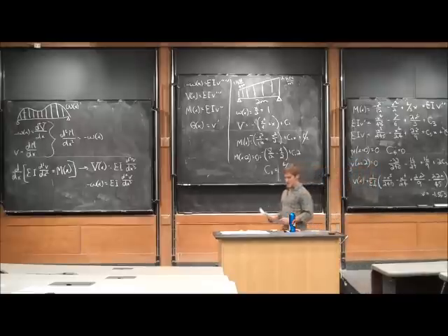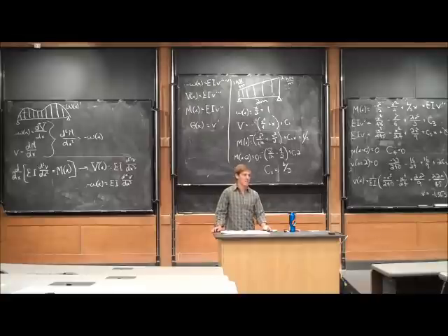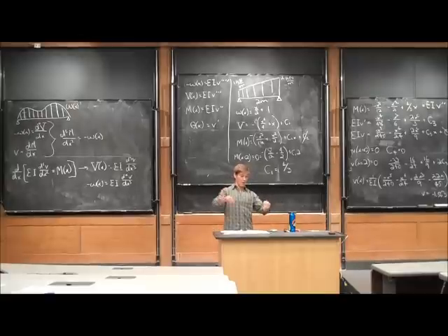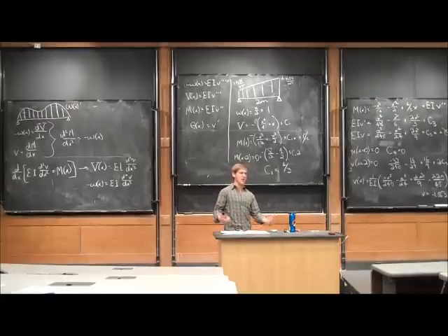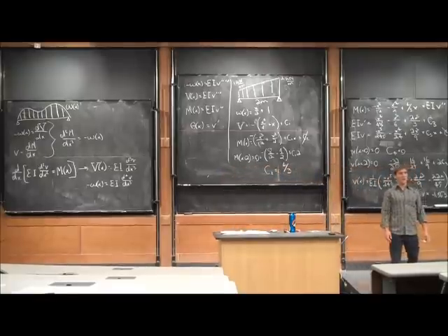It should be several orders of magnitude smaller than the length of the beam. If you look at very thin beams that can deform very much and then come back again, this is not valid for sheet metal. It's valid for beams, I-beams, wooden structures, things that are in the linear elastic material property range.